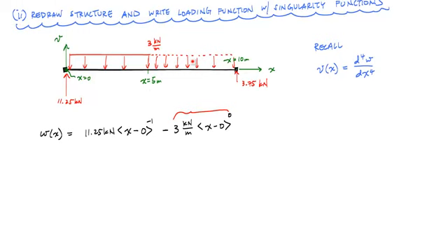So what I've got to do is neutralize this portion of the distributed load with another distributed load that goes upwards here, and basically by method of superposition that tells me that for this length of the beam my distributed loading is 0. I have to use the method or principle of superposition. So I'm going to have another term here.